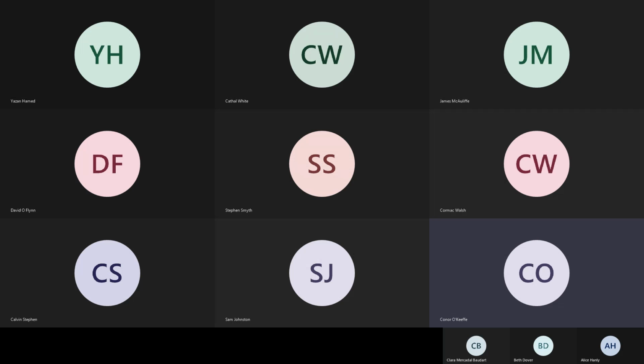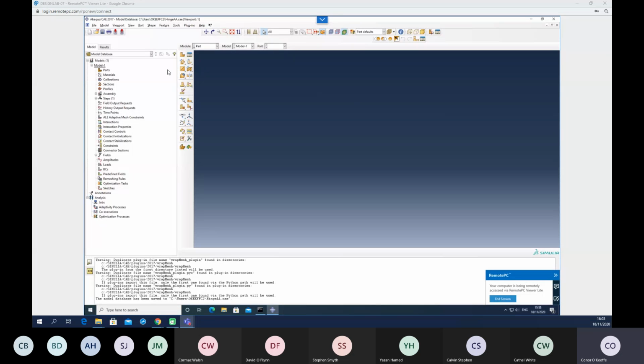So you'll have to submit a report for this assignment, and it's through mesh convergence. Basically, whenever we run a model in Abaqus, the accuracy of our outputs from that model will be somewhat dependent on the density of our mesh. A denser mesh will lead to higher accuracy, but you eventually will reach a threshold whereby increasing the mesh any further doesn't really give you any further accuracy.